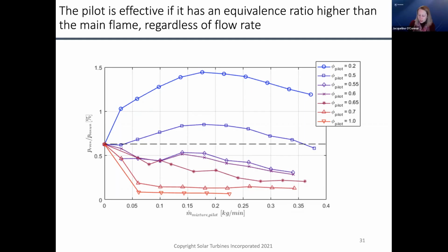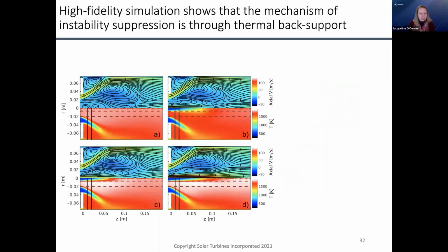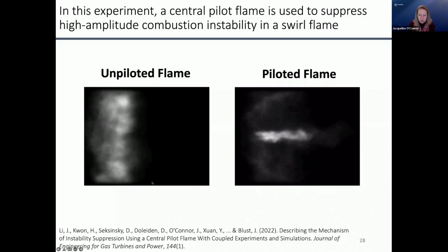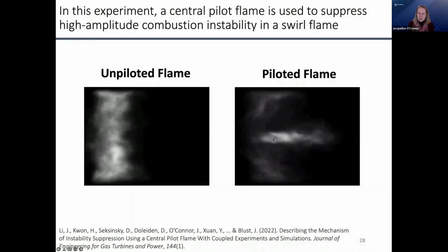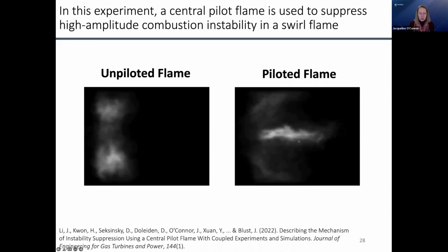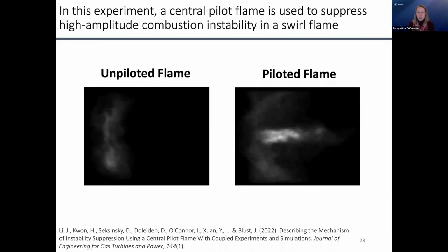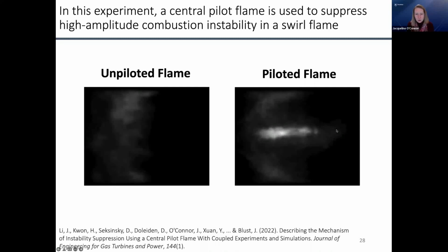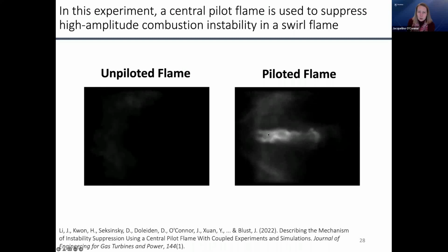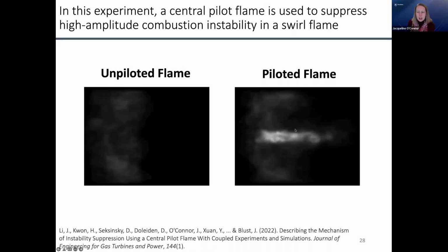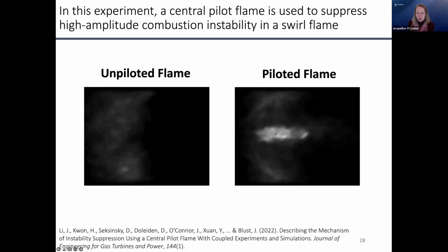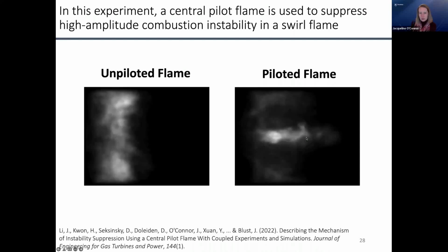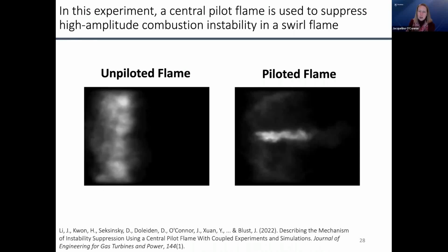Yeah, so really, I don't know if I have a flame picture here. These flames are pretty compact, right? And this video is a good example. I think this is 10% of the fuel diverted to the pilot, which is a crazy amount of fuel. This is a NOx factory here. You would not do this. This pilot probably has an equivalence ratio of 1 or something. It's massive. So the majority of the length of this pilot flame isn't helping.